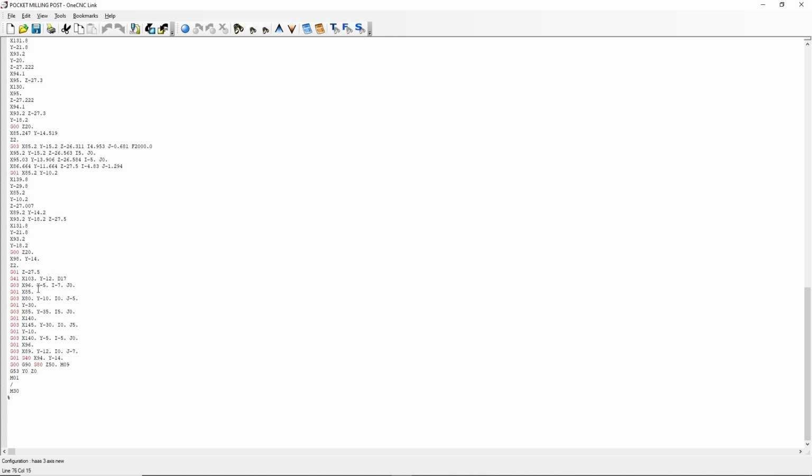It's going to arc on, look, Y-5. So this, remember, this option here is your cutter comp control with G41, and it will program it to the exact numbers on the model, and your offset page will offset the tool for you because you've told it to with a G41 and a D value.